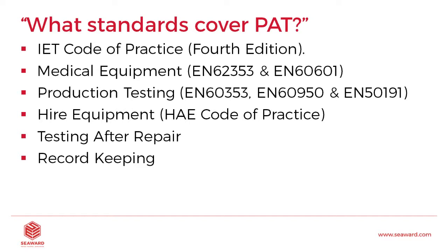Hire equipment then also has its own code of practice and guidance notes. This is produced by the Hire Association Europe. They have their own code of practice, but it's very much based around the IET code of practice. And then you need to look at various scenarios. If you're testing after repair, again that all needs to be logged and carried out to the relevant standards.